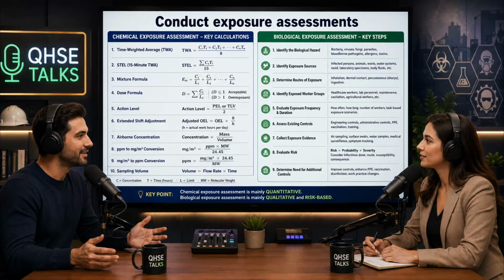Precision and cross-sensitivity. They have a fairly wide margin of error, sometimes plus or minus 25%, and occasionally a similar chemical in the air can trick the reagent into changing color, giving a false high reading. So they aren't perfect. For rigorous, legally defensible, highly accurate compliance monitoring over a full shift, professionals utilize vapor monitor badges. These are the little plastic discs you see clipped to a worker's lapel, sitting directly in their breathing zone.